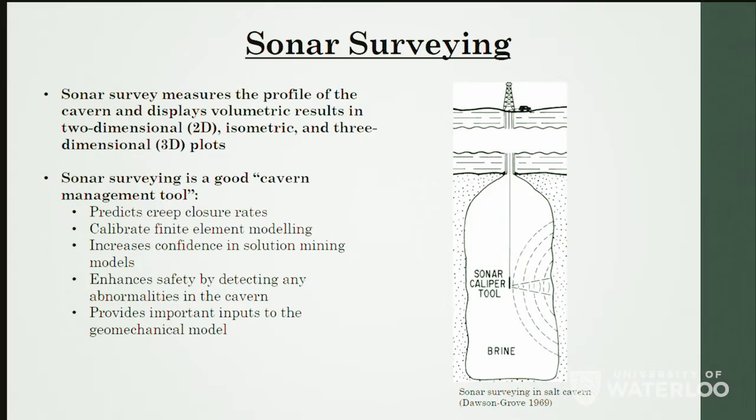If we measure the profile of the cavern today and then we measure once more in 10 years, we can actually calculate the volume change, and that will give us the creep closure rates. And the other benefits are it can calibrate finite element modeling, it can increase confidence in solution mining models, it can enhance safety by detecting any major damage in the cavern, and it can provide important inputs to the geomechanical model.